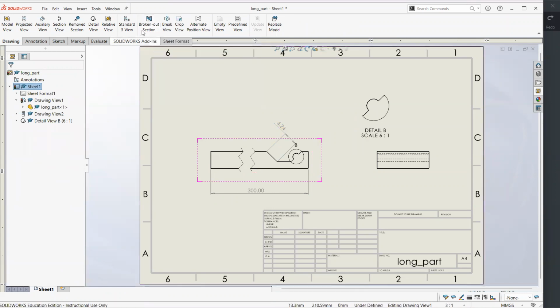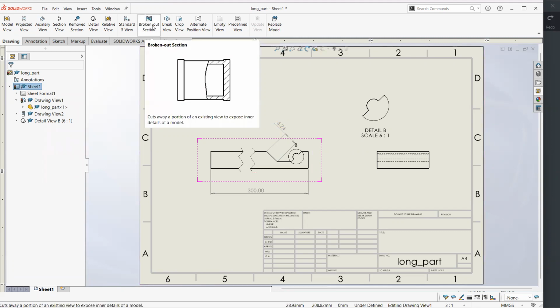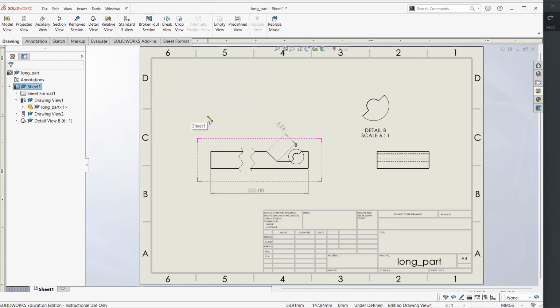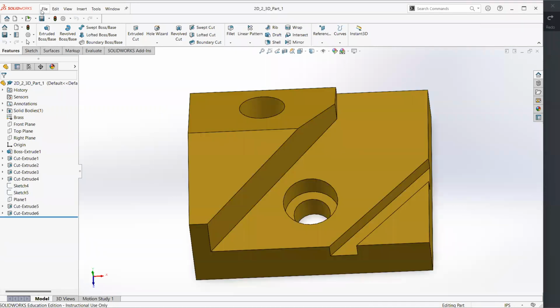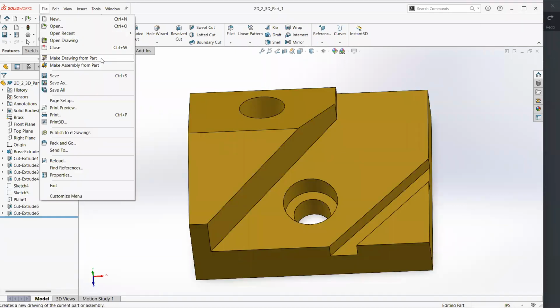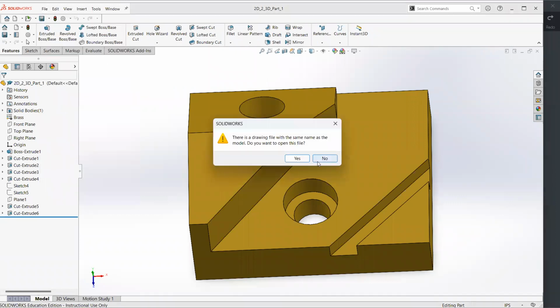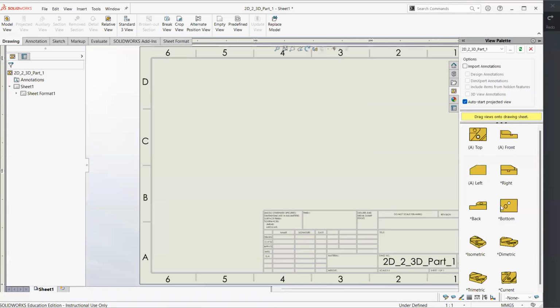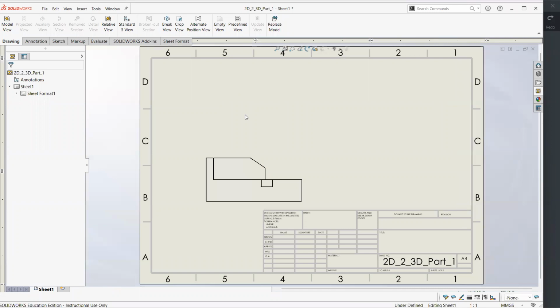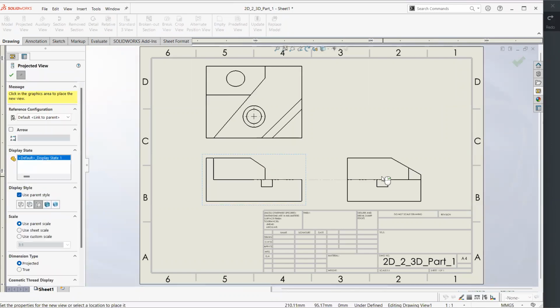And the last view that is most of the time used, but here this is mostly used in assemblies or in tutorials on how, for example, parts are built, and not used a lot for manufacturing, is the breakout section. So if, for example, you go to our first part and again make drawing from part, okay, we could go, for example, to the front view, top and right.